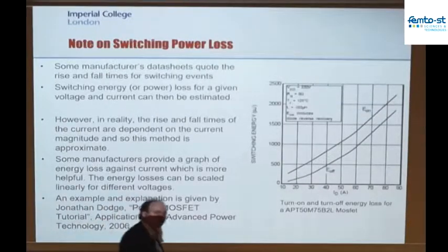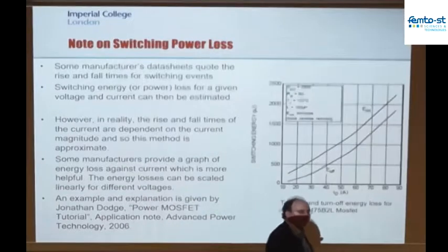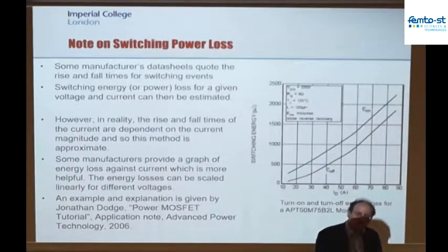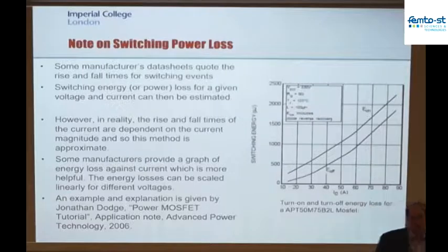But there are other trade-offs, as we already mentioned. If I want to have a small value of inductor, physically small capacitor, then there's a push to want to move to higher frequency. So again, there's a whole bunch of optimization here to start thinking about where exactly do I want to pitch my design.